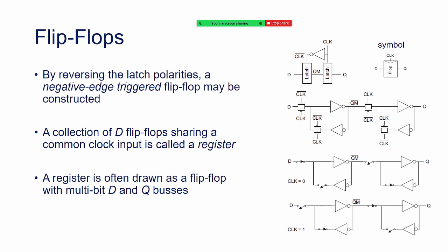Yeah, just one last slide that I want to show. Just like in the previous slides, if you reverse the polarities of these clocks, wherever you see CLK bar goes to NMOS, create another circuit where CLK goes to NMOS, and do that for every pass gate. Then we'll see that this circuit works as a negative edge triggered flip-flop, 1 to 0. The logic diagrams, these switch diagrams will change then.